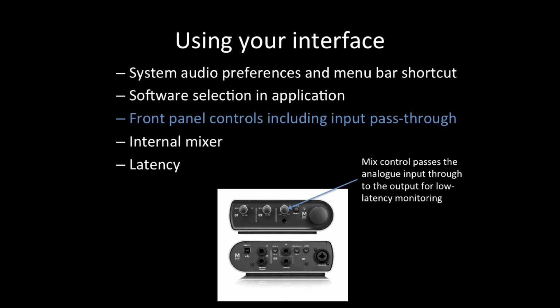This control can provide problems when using the device for live performance. When the control is turned fully counterclockwise, any signal at the input is passed directly through to the output. When the control is fully clockwise, only the signal that is played back from your audio application will be heard at the output. When the control is between these two positions, a mix of the playback and the input can be heard at the output.